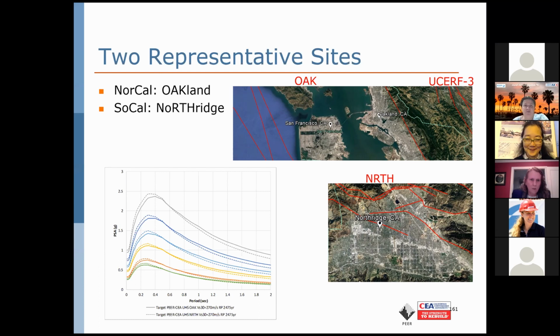And so this was a really important consideration as to what do we do? Do we represent these as near field sites because the one location is in that area? And so we decided to smear our ground motions to make sure that we included near field characteristics as much as we included not so near characteristics. Of course, LA, everything is in the near field.